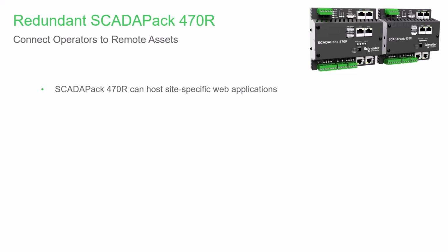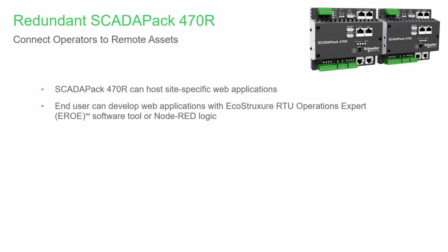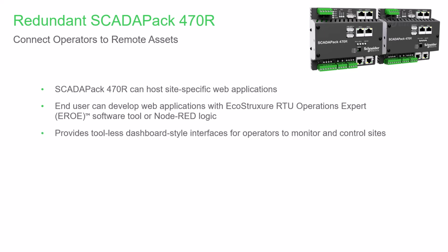The redundant SCADAPack 470R helps to connect site operators to their remote assets, as the 470R can host site-specific web applications. End users can develop web applications with the EcoStruxure RTU Operations Expert, or Arrow, software tool, or with Node-RED logic. This can provide tool-less dashboard-style user interfaces for operators to monitor and control their sites. Operators can use a browser on their phone, PC, or tablet to connect.